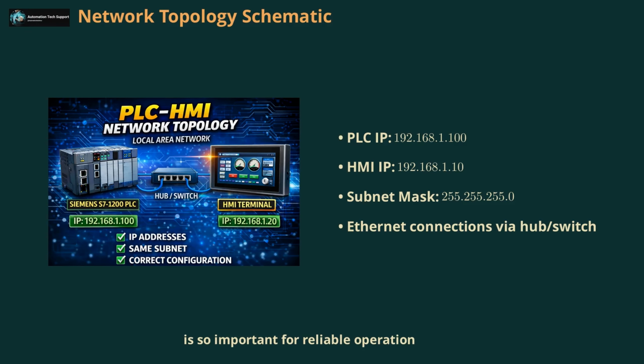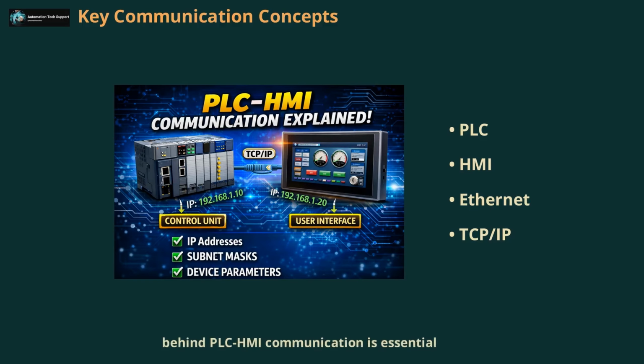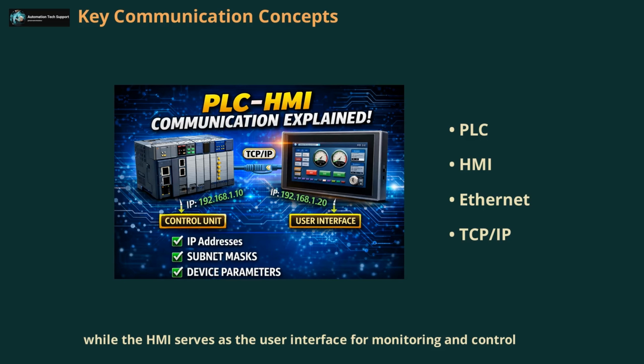for reliable operation. Understanding the core concepts behind PLC HMI communication is essential. The PLC acts as the control unit, processing inputs and outputs, while the HMI serves as the user interface for monitoring and control. Communication is established over Ethernet using TCP/IP protocols. Proper configuration of IP addresses, subnet masks, and device parameters ensures data can be exchanged reliably and securely between the